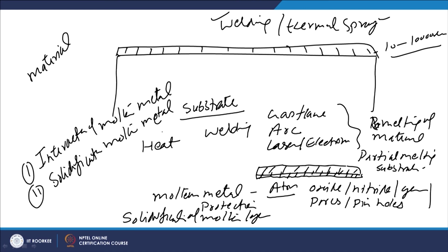At the same time, some of the heat applied during welding for surface modification, whether using a gas flame, arc or laser, is also transferred to the underlying base metal, and that is why, especially in the case of hardenable metals, it forms a heat affected zone.